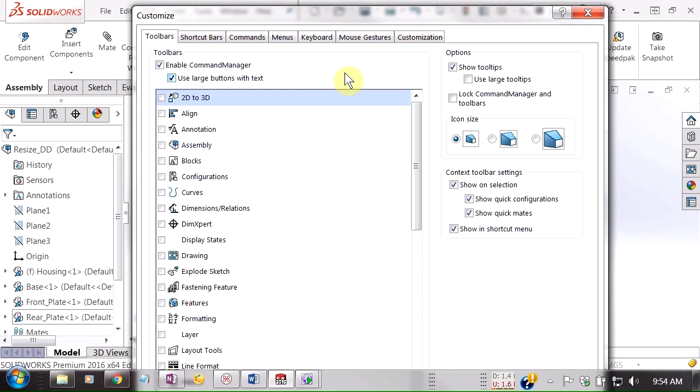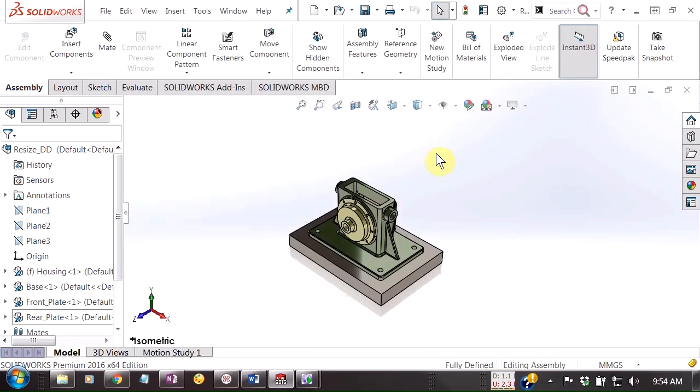So the Copy Settings Wizard is going to export a chunk of your registry that saves these settings so you can save it as a backup. The reason why you do this is a lot of things can cause SOLIDWORKS to go back to the default settings. So maybe your computer crashed, maybe you had to reinstall SOLIDWORKS, you got a new computer possibly, anything like that, and you might go back to the default settings essentially.